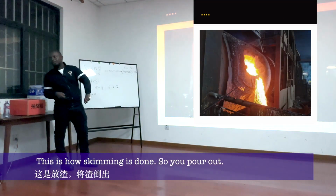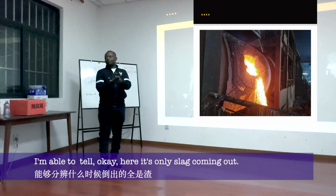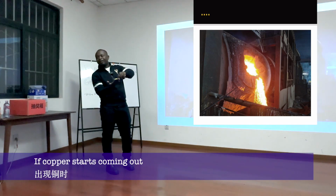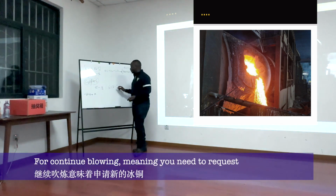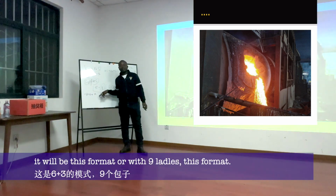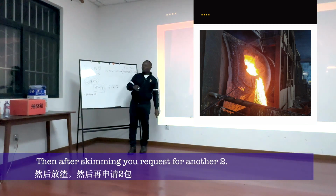This is how skimming is done. So you pour out. So for me, who is experienced, who knows the composition or how it looks, I'm able to tell, okay, here it's only slag coming out. If copper starts coming out, it will indicate now slag is finished, now copper coming out, stop, you continue blowing. For continue blowing, meaning you need to request, if you are completing the cycle with 9 ladles, it will be this format, but if they say 10 ladles, you can just request for 2. Then after skimming, you request for another 2.